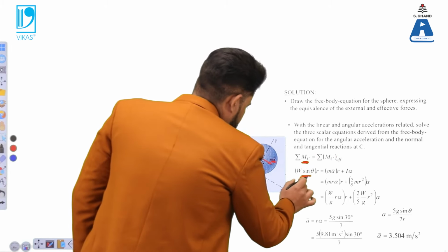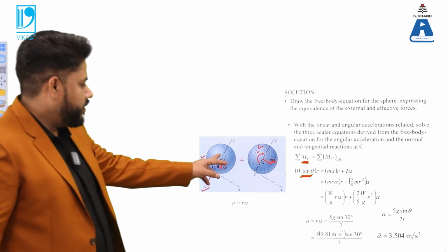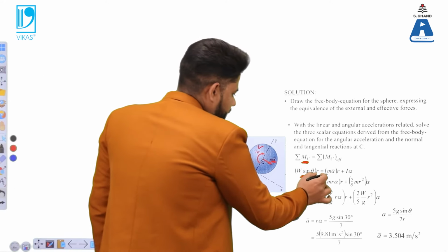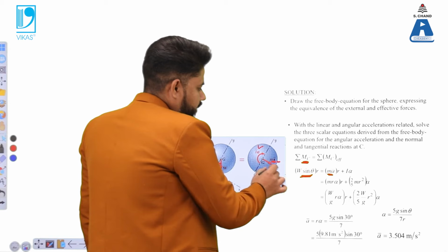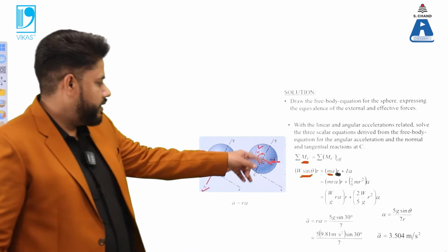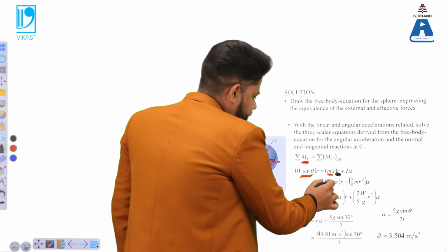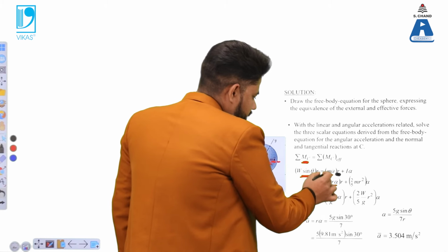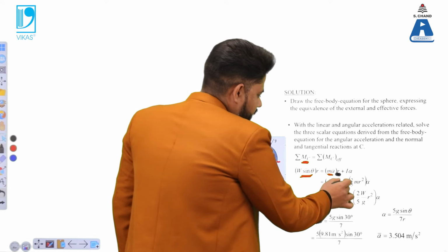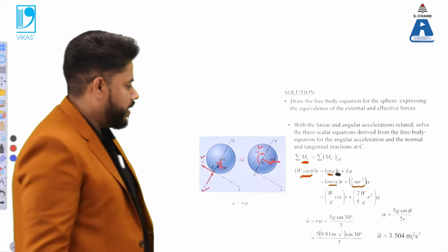So what we will do, we will create this W sine theta component. So the vertical component of this would be the W sine theta multiplied by the distance it traveled, and MA is this force component multiplied by this distance it traveled, plus the moment. The moment is I alpha. So putting in the values like R, we have multiplied it here, m R alpha into R plus, in I's place, we have to write 2 by 5 m R square into alpha.